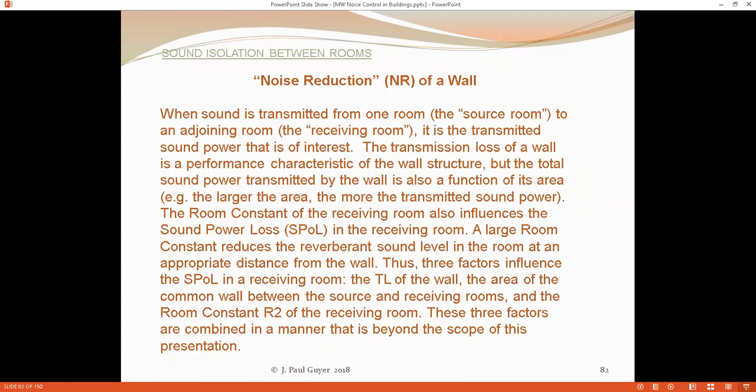There are other issues that crop up in building design. One point to keep in mind is that ductwork in air conditioning systems provides a pretty convenient path for sound to get from one room to another. In particular, where this often crops up is in the fan room. The fans are noisy. Some of that fan noise can be transmitted through the duct system into the occupied spaces.